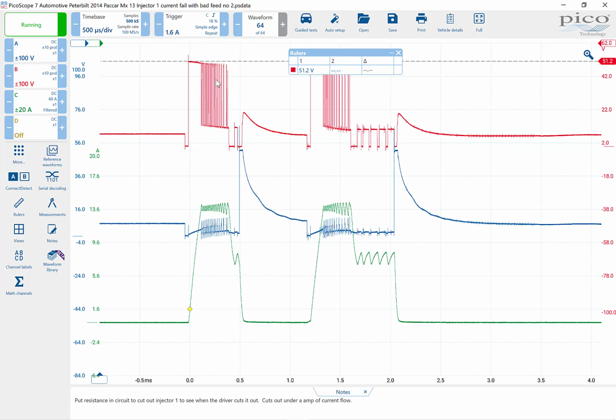It's a little bit different, because on these types of injectors, the way they get the voltage to fire at 51 volts is due to capacitor banks inside the computer. Normally, from everything I've seen, and on this one too, you have two capacitor banks in charge of firing 3 injectors per bank. Alternately, the computer gets a charge from the ground side on this inductive kick, which is going up to around 50 volts, and that is used to help charge the capacitor bank back up. So it's constantly alternating between banks and injectors to have enough voltage to dump into the next injector in the firing order.